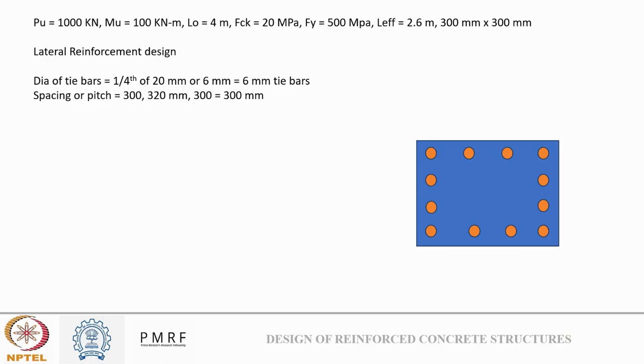Okay, just to show you what I was saying about that lateral tie bars. So you can provide either like this one complete, or you can provide with this one complete, one like this also, and one like this also. Okay, so these three kinds of ties, so this will run, then 6 meter above that, 300 above that, one lateral tie like this, 300 above that, one lateral tie like this, then again this one lateral tie. Okay, so this is how you can also provide the reinforcement detail. Okay, I hope this question is clear to everyone.